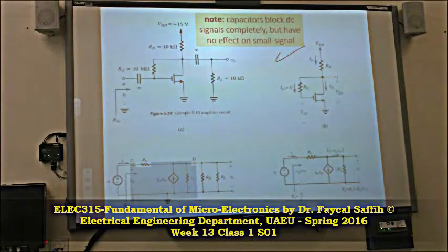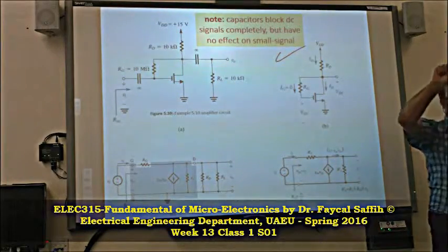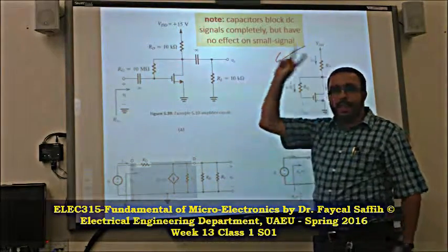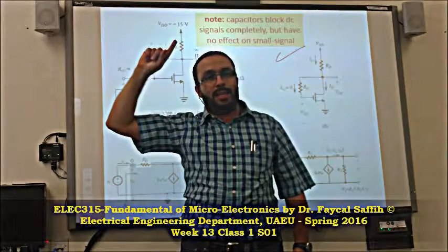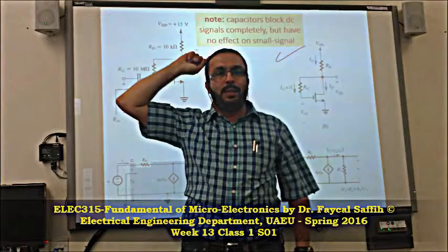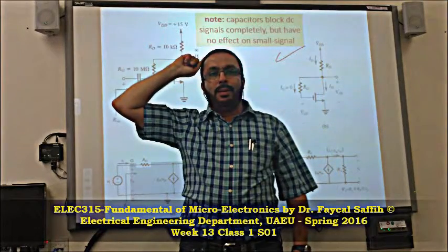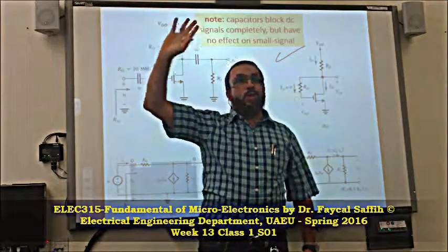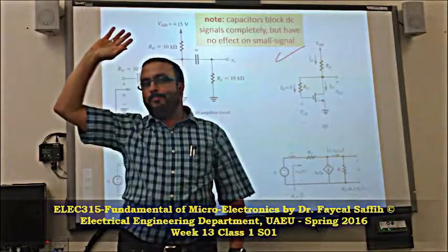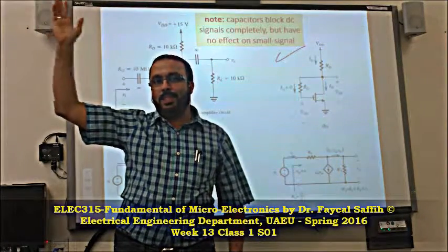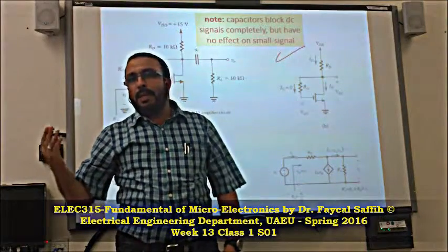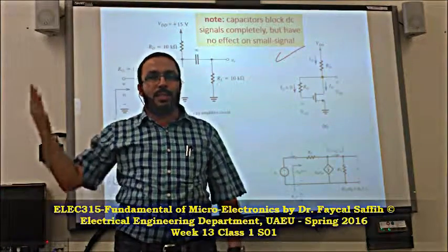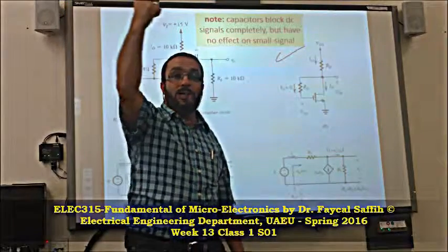When we analyze the transistor, we have to do two analyses: the DC analysis and then the AC analysis. The DC analysis, what's the benefit of it? So far, what did you study in the amplifier? GM. GM is an important parameter, and we get it from the DC analysis, because in DC you have the overdrive and the current ID.